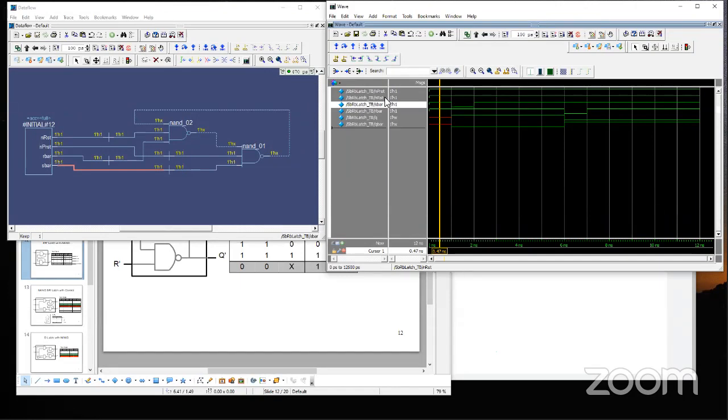From the hardware point of view, a reset signal goes into all the individual logic gates and flip-flops and sequential elements, like preset and reset, and that signal flows into these components and gets them into the known initial state condition. That is really what the reset button was in the old computer system, and now it is a soft reset.